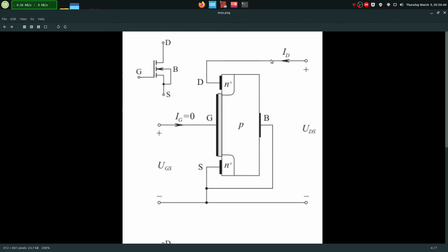This is an N-type. You can recognize it because it has current flowing into the drain and out of the source, and the N-doped semiconductor parts connected to the connection points are N-type, and the substrate is P-type. Because this is N-type, the majority of the current carriers are electrons. These conduct current very well, and the channel induced by the voltage applied to the gate is going to create a channel of electrons, and it's going to create a current flow.